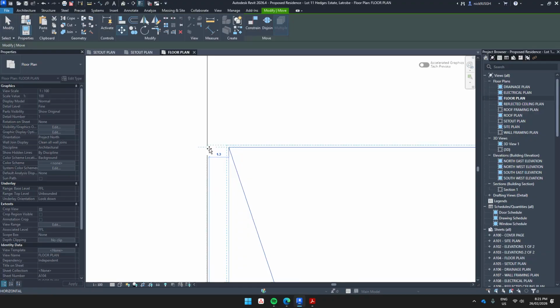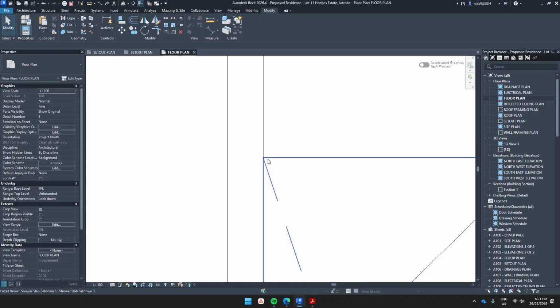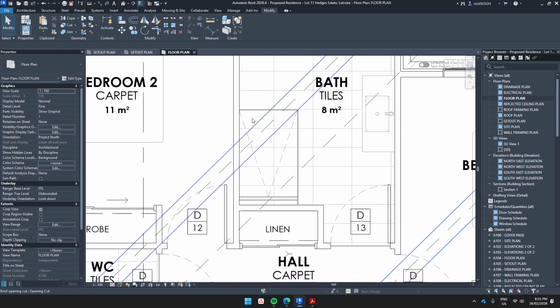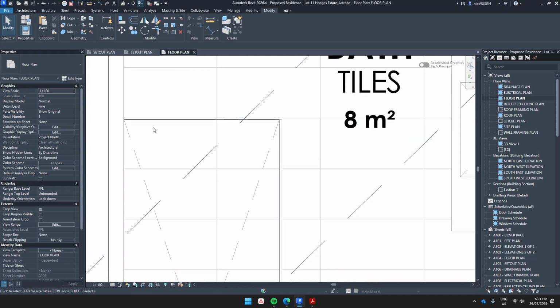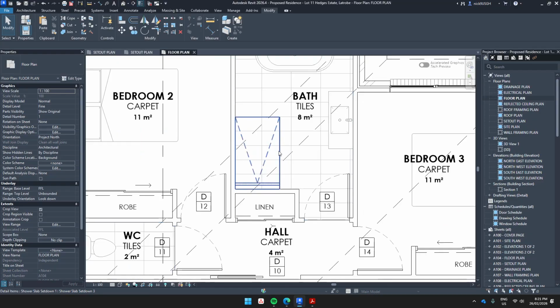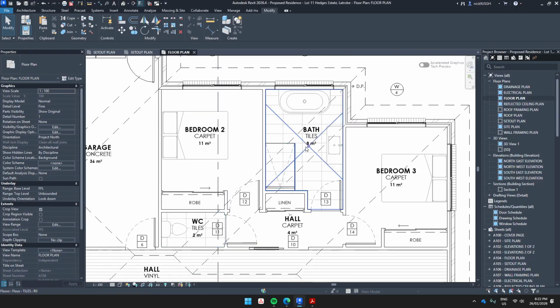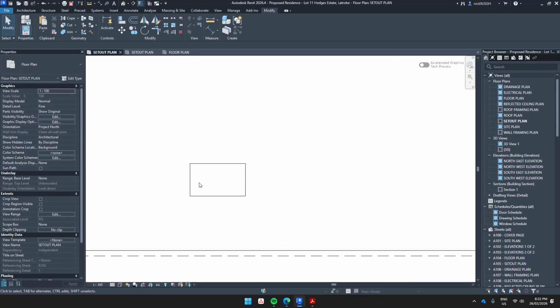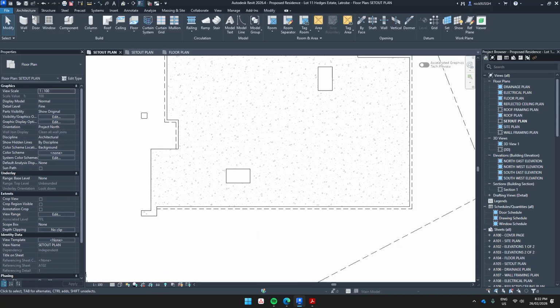If you ever see a shower that's not quite those measurements, we need to make sure that they are at least that big, otherwise they need a door on them. So if you see a shower that's 1200 by 900, feel free to question it, because in most cases they should be like this configuration. Cool. So we've got our showers, but now we've got a couple of holes here, which is less than ideal.